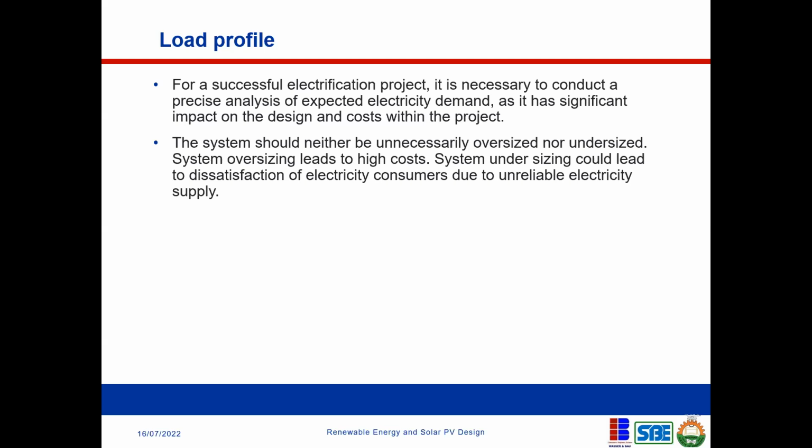Okay, people want to buy a generator, they say, my neighbor is using 500 kVA, let me go and buy 500 kVA. It's a lie, they're not the same thing. People buy generators based on mere estimates without engaging engineers to do a proper load audit and advise them on the right capacity to buy. So you find people have generators that are operating at less than 30% of the load factor. You have a generator that can do 100% work and you're using only 30% of it.